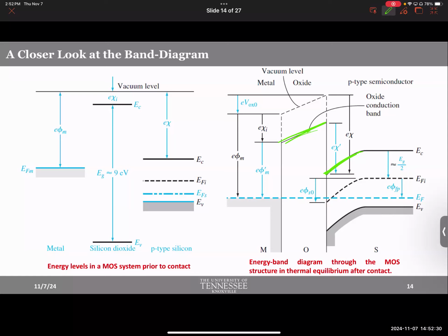Okay. There are exceptions. There are some unique fancy devices that people developed, and I worked with one of them in my PhD. It's called a negative capacitance transistor. That could actually break this rule. But without that, chances are you will probably not have to deal with it in regular form. So it could be a general rule of thumb that the oxides will always bend in the same direction as the semiconductor. So I hope you can easily remember it now.